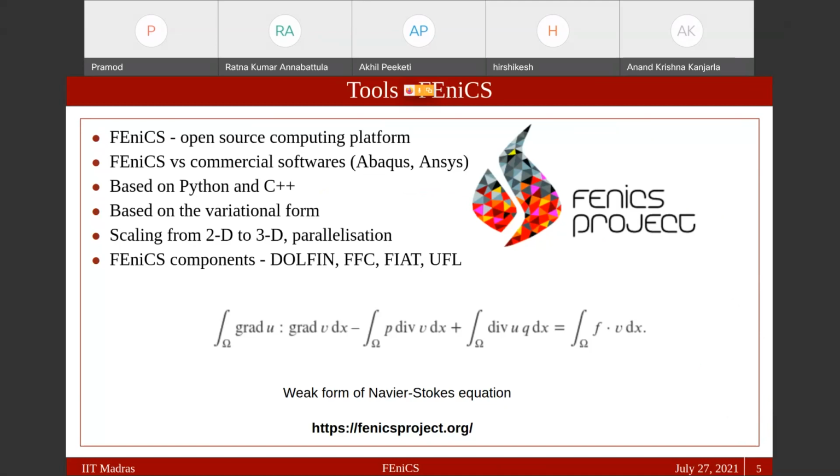Okay. Thanks. So where does FEniCS stand compared to Abaqus and Ansys? See, Abaqus has certain advantages. Some of its contact algorithms are really very robust. Handling nonlinearity, especially constitutive nonlinearity such as plasticity, especially for an established model, can be quite an easy job in Abaqus or Ansys. Large deformation and shell elements can be quite easier. The learning curve is not as steep as when you code from scratch, compared to using the software Abaqus.